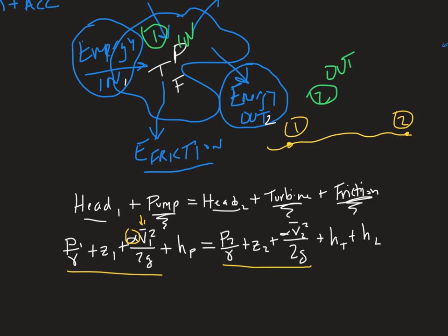However, when we're dealing with a control volume, it's the energy going into the control volume. So it could be an opening, and you can imagine that the velocity has a profile. There's not just one velocity, there's a velocity over that whole opening, which is totally annoying. But we don't want to have to integrate. Normally you would have to integrate all of that in order to get at the total energy going in.